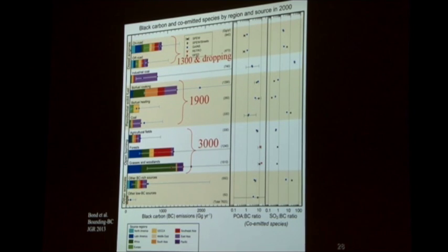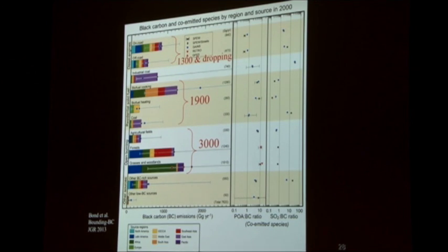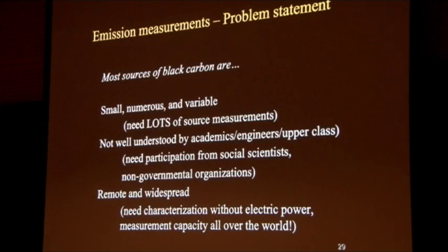My student named it the Fumatron. What we have is CO, CO2, and particulate matter in real time. You can have black carbon or absorption in real time, and you can also, with filter holders, collect mass and OC/EC. If you put small batteries in, you can run for 24 hours without electric power, then you have to recharge.